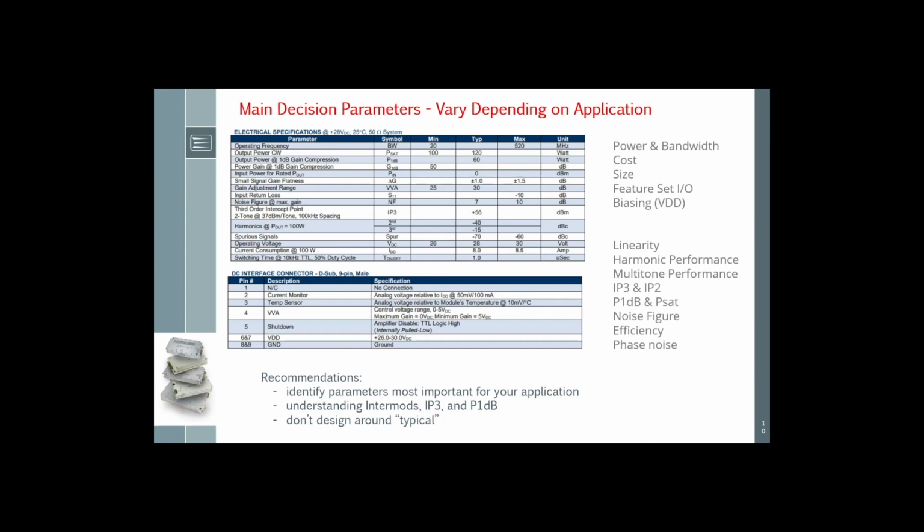It's not going to be the 1 to 2 variation that we usually think about when we are talking about a Class A amplifier or low noise amplifier. So please find where the specification is being done, and usually see the intermodulation at minus 6 dB per carrier from the nominal power.